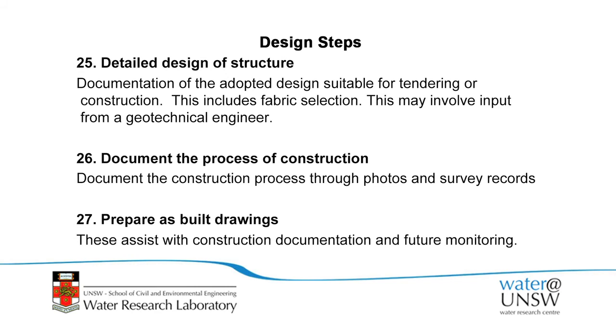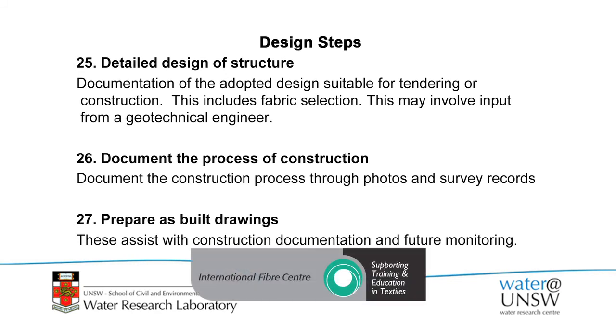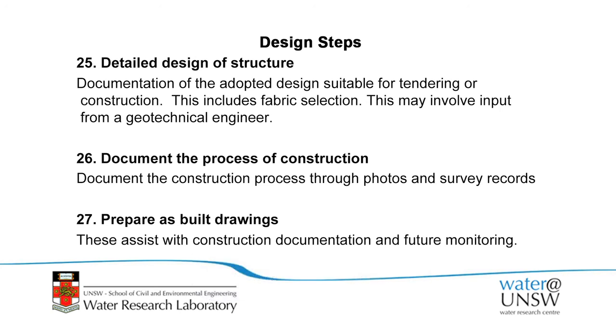Assuming that's all happened and you've commenced building your structure, document the process of construction through photos and survey records. Because these are often temporary structures and the life of them well exceeds what they were designed for, and they're often in contentious coastal areas where there are difficult decisions as to what the long-term strategy is. Like any coastal structure, it can often end in litigation, and I have been involved in several cases where there's a big argument about what was actually built, because it was built 10 years ago, no proper records were kept, and then there's a big argument about what was built.